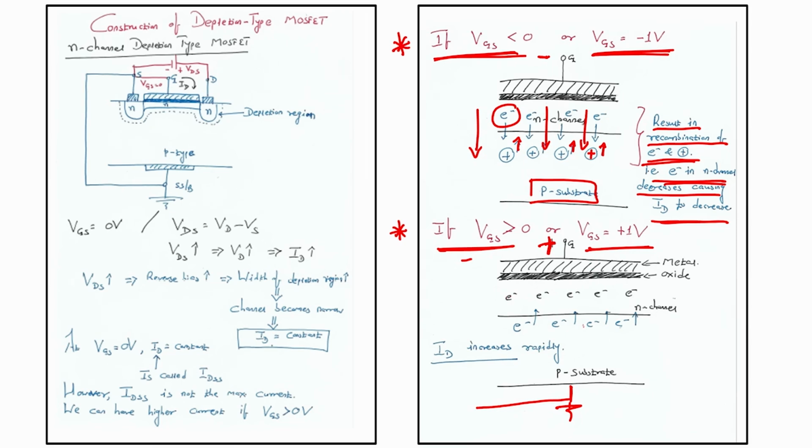The electrons in the substrate will be pulled up. The n channel is already there. You see here the n channel, these are electrons within the n channel, alright. This forms the channel between source and drain. This is your oxide layer, SiO2, a thin layer of gate oxide. We already have seen how we can grow gate oxide, using thermal oxidation, right.